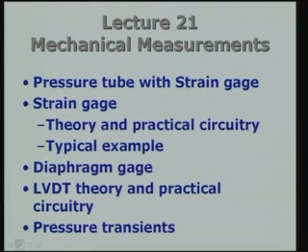And we introduced some elementary ideas regarding this, including the LVDT. We discussed in very brief the nature of LVDT and how it is used to measure a deflection or a distance, which is the deflection due to the action of the pressure. So, in other words, the pressure signal is converted into a deflection or a length, and this length is measured using either the LVDT or a strain gauge.